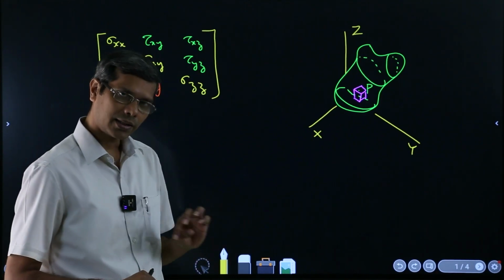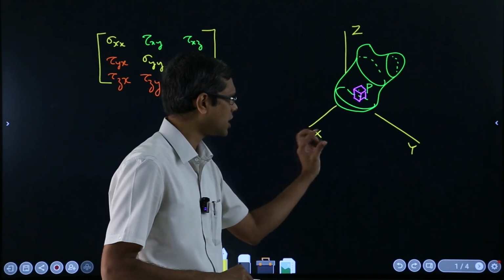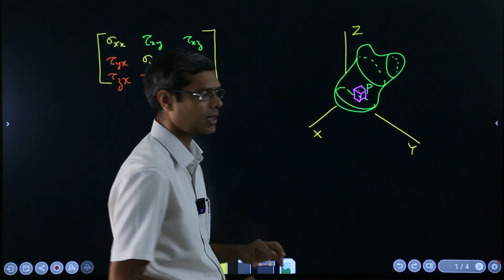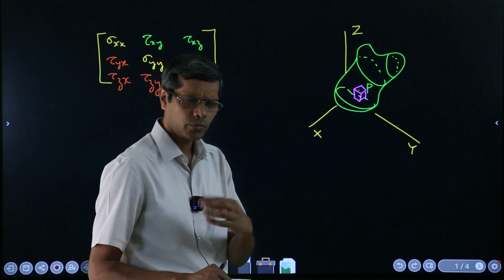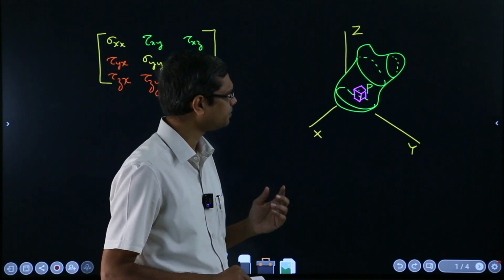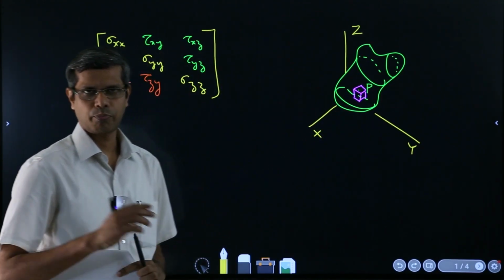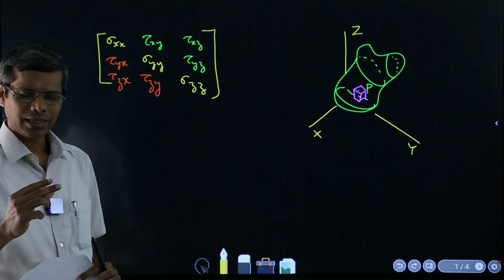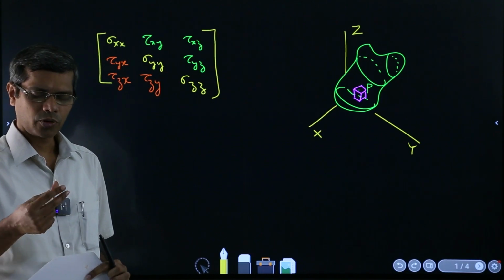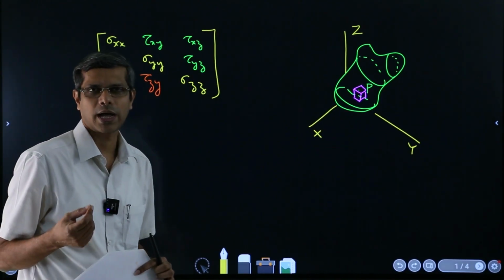So that's the main way to decide whether a body or a system is safe or not safe. This is one way, when I said that you change the coordinate systems and see how these components are changing around. Or else, another viewpoint is this cuboid which we picked around this point P, that we keep on rotating, and we see the stresses which are moving on that.